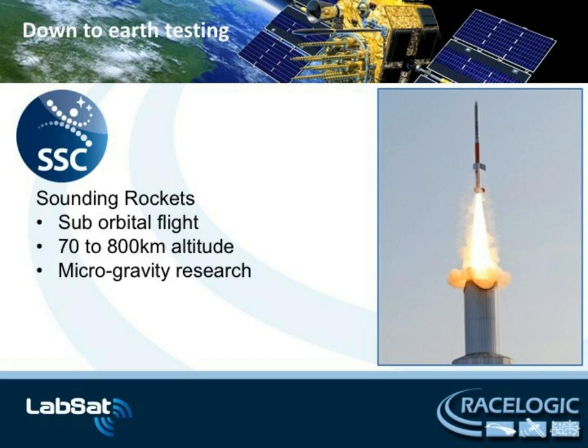Interestingly, when the rocket launches, it is deliberately designed to spin to stabilize its attitude. This creates a very challenging set of conditions for GNSS. Not only does it have to work at the high speeds and altitudes, but it also has to cope with a high acceleration, jerk rates, and yaw rates. The spinning also introduces a phase shift in the satellite signals, which has to be tested on the ground before being used in a launch. This phase shift can skew the measurements and also make tracking of the satellites much more difficult.